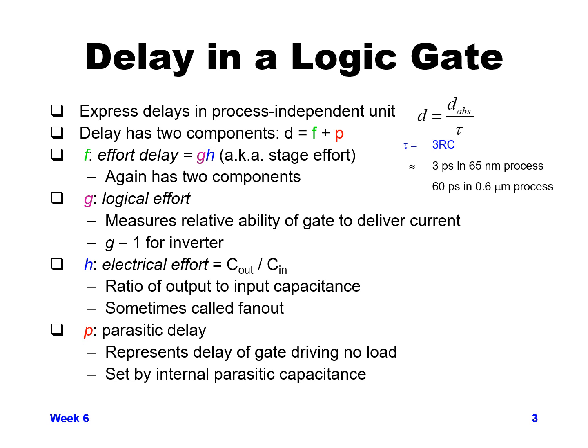And then finally, the value of P, because we have F plus P is the value of your delay. That's your parasitic delay. This is the delay for a gate that's driving no load. So it's the minimum delay that you'll ever have through a given gate.